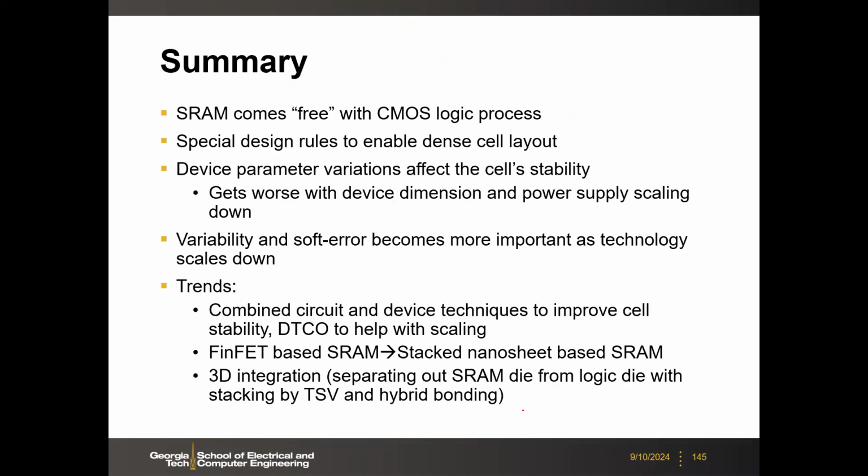So here, this is a summary for the SRAM lecture. SRAM is compatible with the CMOS logic process. Of course, the design rule may be a little different, but the transistor itself is the same as a logic transistor. If it's FinFET, then SRAM is also FinFET. And then the variability and soft error are critical for the SRAM.